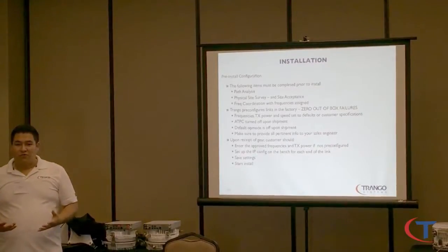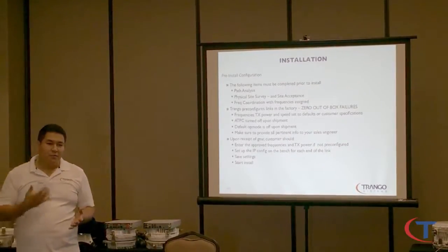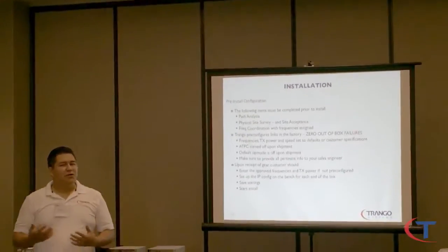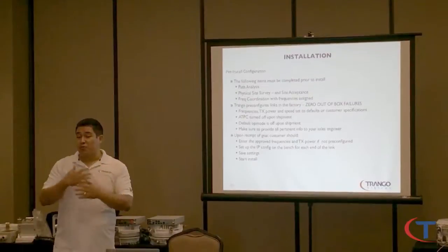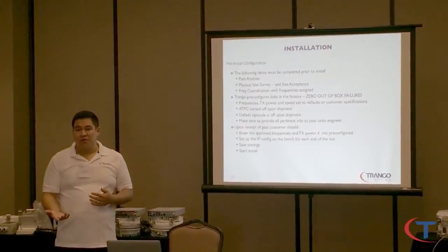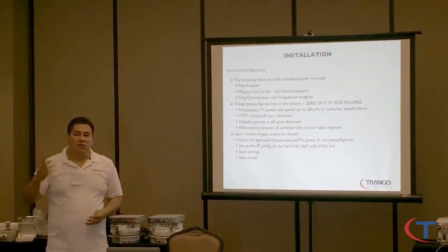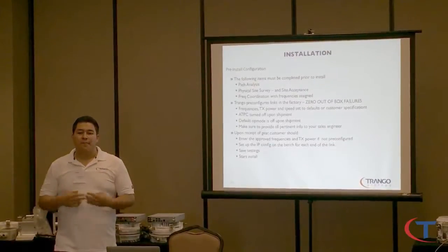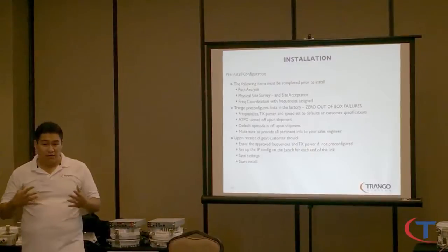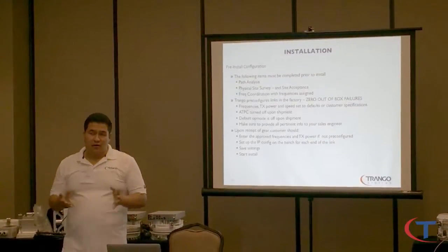Site acceptance. If you're gonna lease, you want the best thing because you're gonna pay for it. Typically, it's gonna be out there, American Towers, big infrastructure. If you go into a private tower on the back of a hill, on top of somebody's house, on the hospital building, make sure they have proper grounding lugs outside and the rack space you need.